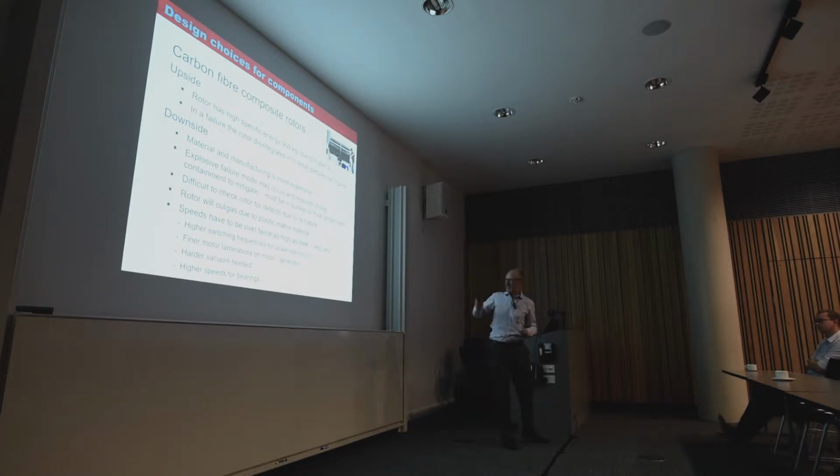There's a number of things, but the other thing is it's got to run at over double the speed of a steel flywheel, or certainly the design I'm working on. So the subtlety is all about the system of the motor generators running at more than twice the speed. That means the power electronics are more expensive because of higher frequencies. The bearings are a bit more difficult. Your windage losses are higher. There's a whole load of challenges, but there are some very good composite flywheels on the market. They're available, and they're working very successfully in both automotive and grid stability.